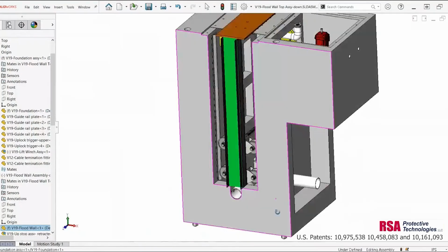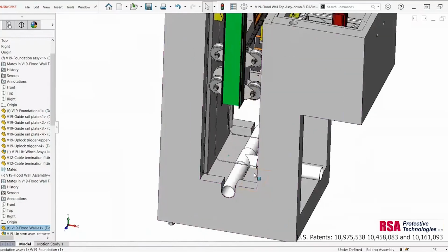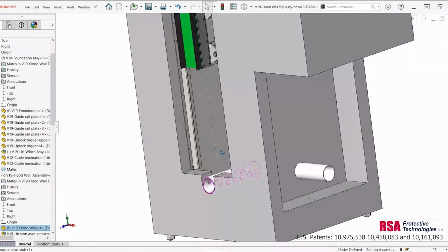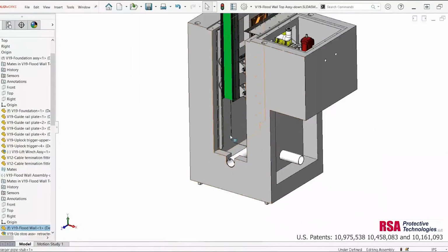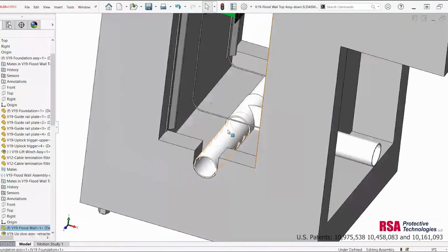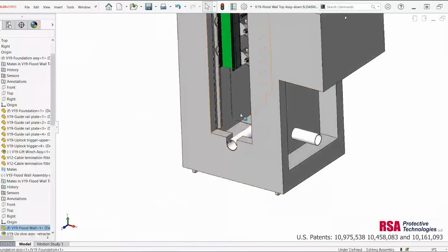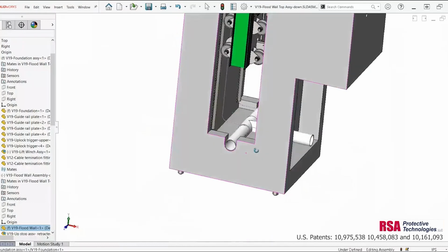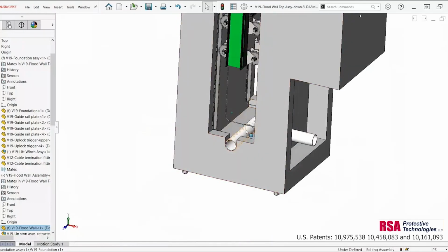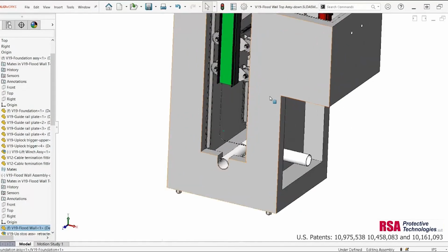There's a plumbing feature here, which we call the sparger pipe. It's a horizontal pipe with holes in it. And the use is to clean out any silt or debris that gets into here. We pump water into here. These are continuous. Pump water into here, and the water comes out of the small holes here on the side and churns up any water that's left in this cavity here. And once it's in suspension, we change the valves out and we use a pump to suck all the water back out again. So that is a way to fairly clean the sump here without actually having to do it manually. So it's an automatic system.